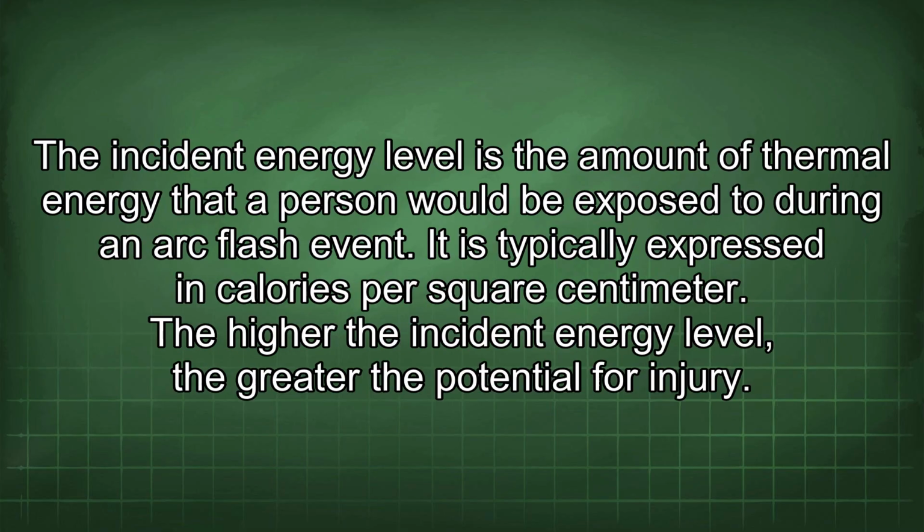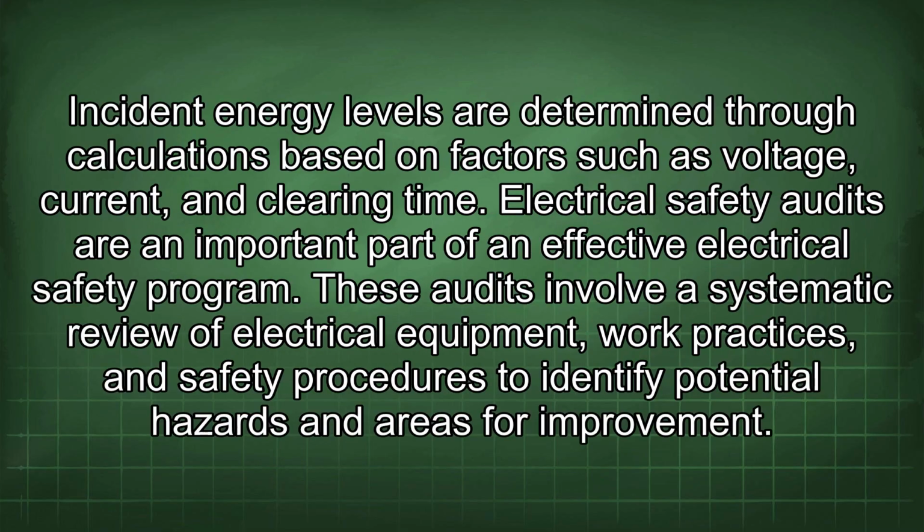The incident energy level is the amount of thermal energy that a person would be exposed to during an arc flash event. It is typically expressed in calories per square centimeter. The higher the incident energy level, the greater the potential for injury. Incident energy levels are determined through calculations based on factors such as voltage, current, and clearing time.